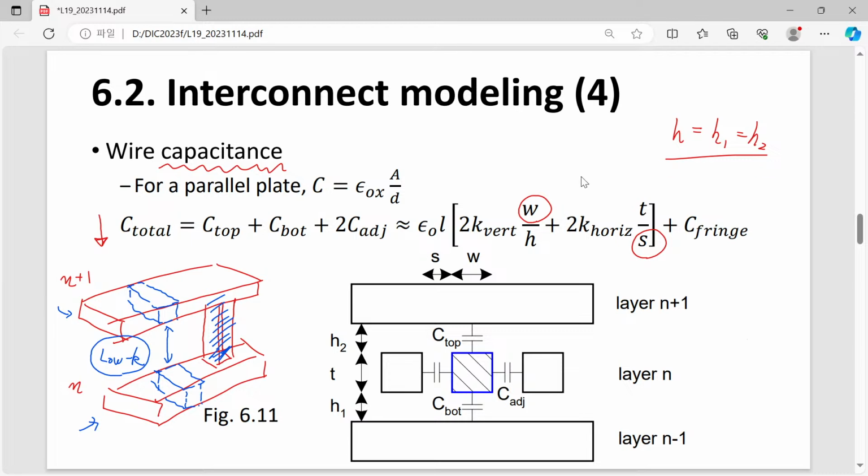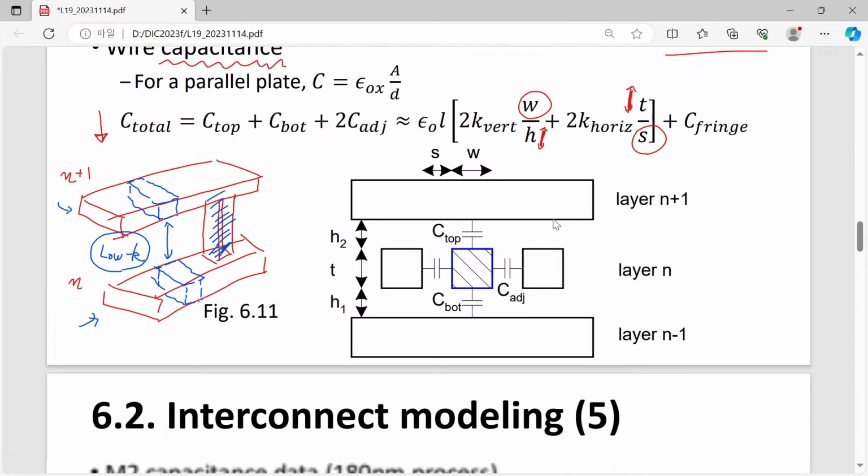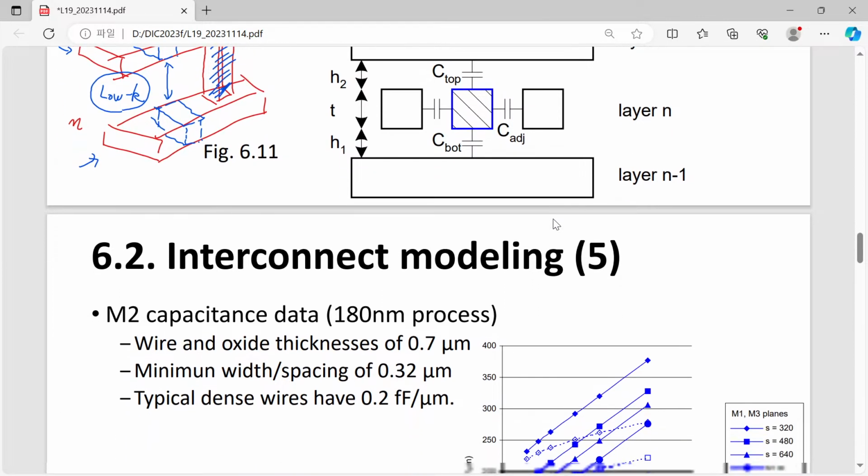Therefore what they do is to play with the thickness and the distance between layers to find an optimal value for these quantities, so that without sacrificing the areal efficiency, we can find a more or less optimized value for our interconnect. So that is the typical way the technology guides that.